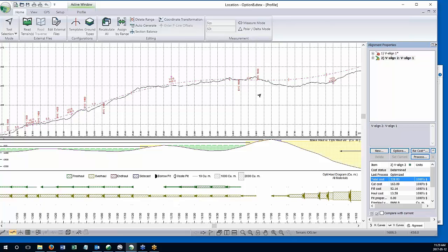In fact, the optimizer doesn't do a great job because in steep terrain, you typically want to move to full bench cut the whole way and go at maximum grade up the side. And the optimizer just simply doesn't really help you with that. Where the optimizer is good is in terrain that's transitioning, rolling terrain. It's very good at that. But as far as optimizing full bench, steep roads, not so good.